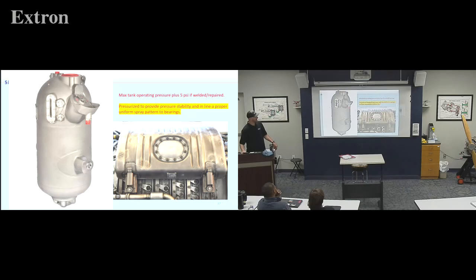Our tank pressure for our oil is usually going to be not much higher than atmospheric. I think in JZ's video he talked like 2-3 psi is all, which seems really low. I thought it would have been much higher than that, but anyway, there's that low number. One of the numbers they want you to remember is if you ever weld a tank, you've got to go test that thing at 5 psi pressure.